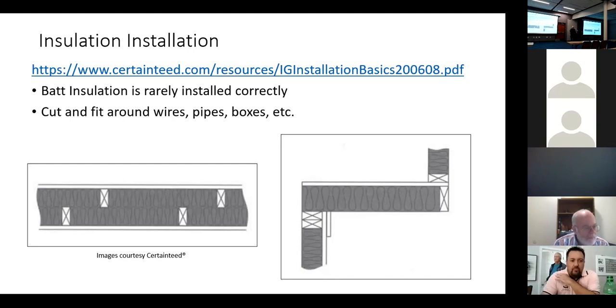And I see so much insulation that's installed just horribly. When you take a thermal camera, you can see it in all these places. So not only do we have a whole 3 foot by 3 foot area in all of our houses, we have 10 foot by 10 foot of poorly installed or almost no insulation because of poor installation practices. So rarely is it continuous.